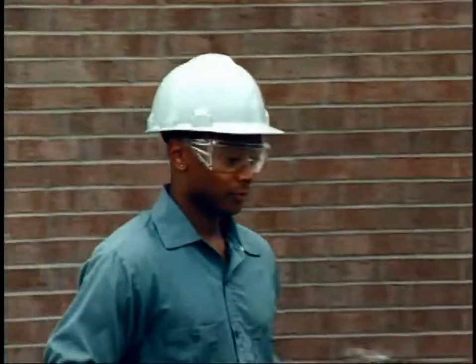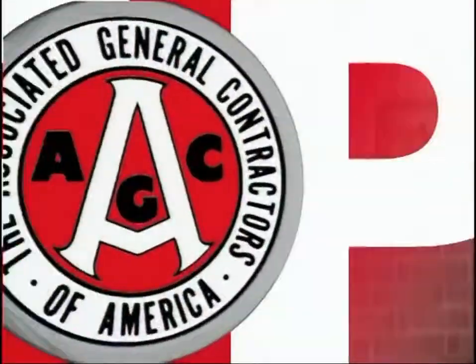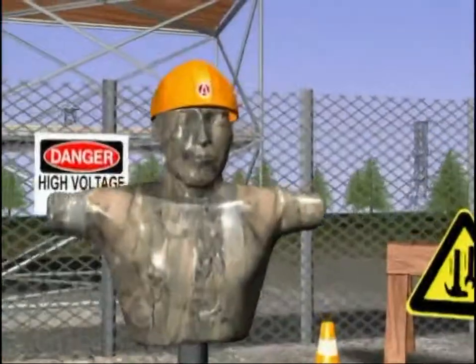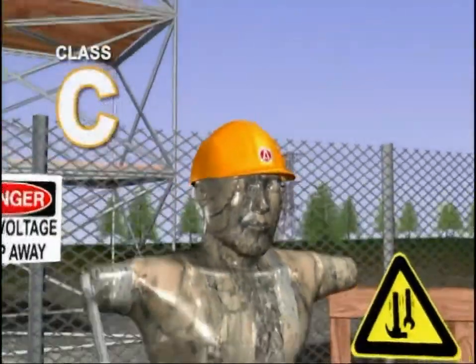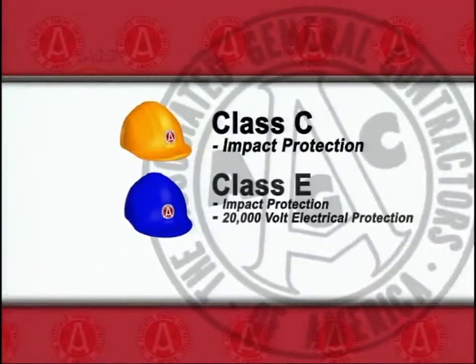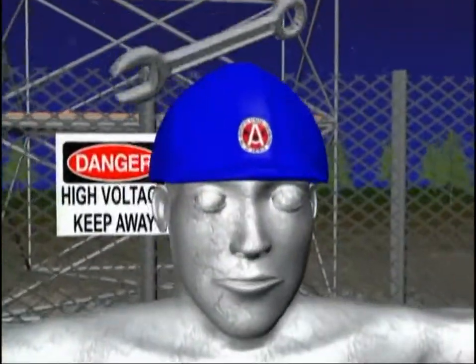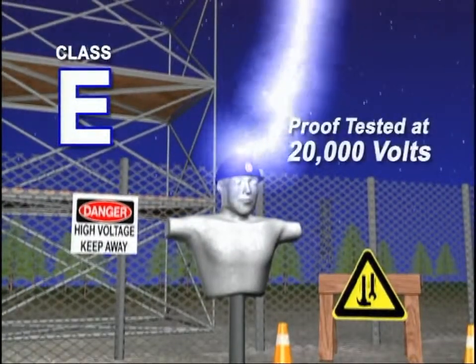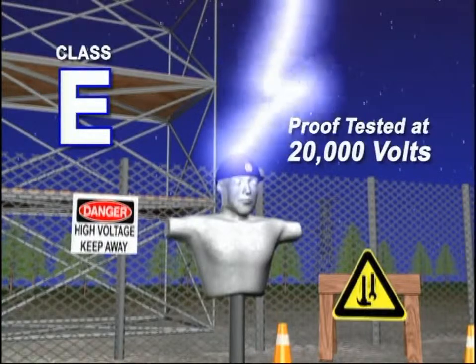Wear a hard hat that is appropriate for the hazard. Class C hard hats are intended to reduce the force of impact of falling objects, but offer no electrical protection. Class E hard hats are designed to reduce the force of impact of falling objects and to reduce the danger of contact with exposed high-voltage electrical conductors. Sample shells are proof tested at 20,000 volts.